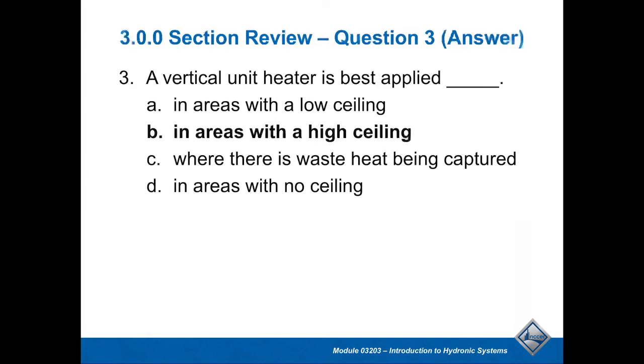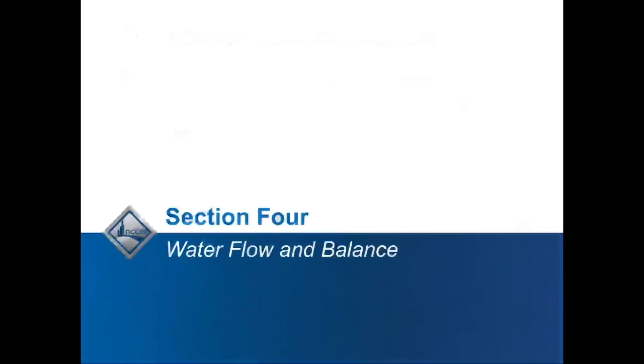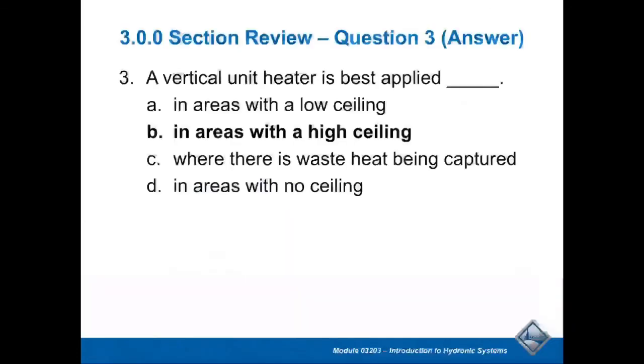A vertical unit heater is best applied in areas with a high ceiling, you might remember this one. Very high ceiling, because you're blowing air straight down, and so a high ceiling would make the most sense. And that is section 3.